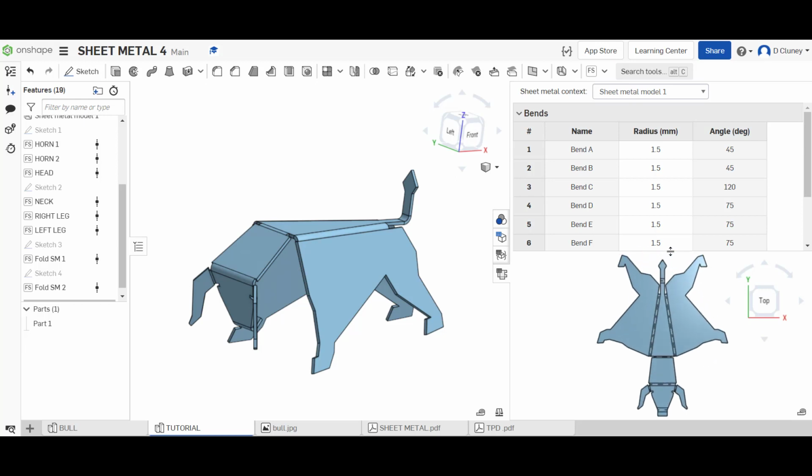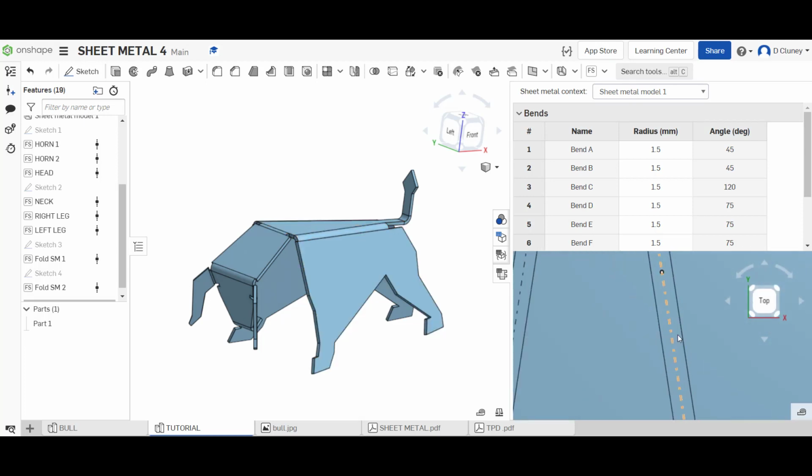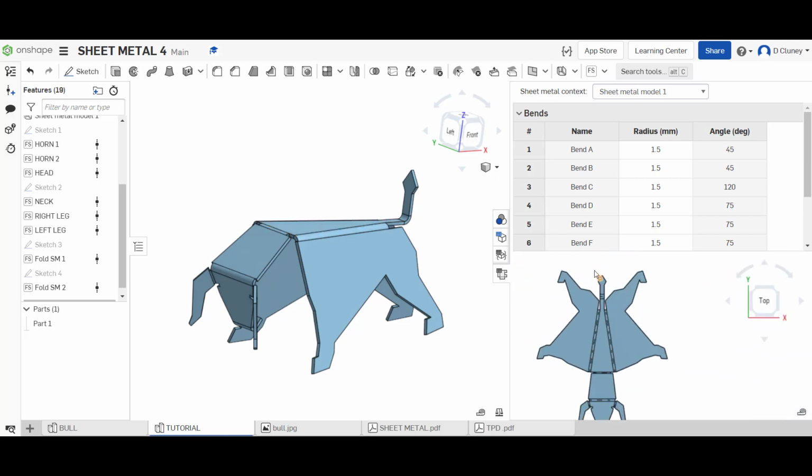And if we click on here, if I zoom out, we've got the overall net of flat drawing. This includes all the bends, so if I hover over anything on the model, it highlights on here, and again if I zoom in and hover and select any of this, again it highlights it on there as well. And we can export that, and we could easily laser cut it if we wish, say something like acrylic, or we could send it, and if we are fortunate enough, we could have a plasma cutter. We could cut that out and then have a go bending it, or even do that by hand by printing it off and create a paper template and then cutting it out by hand and bending it in that way as well.